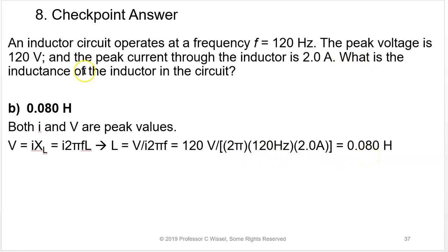Now you have to be careful with this. You can use this as long as they're both peak or they're both RMS. Don't use it for instantaneous values.